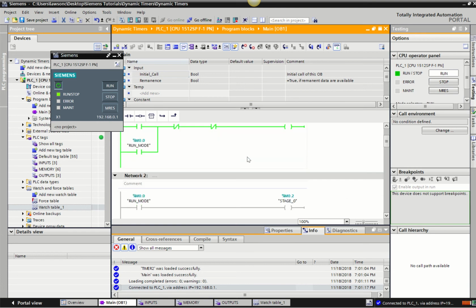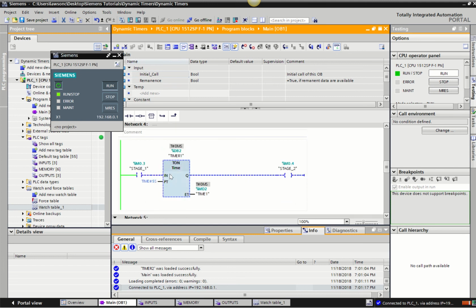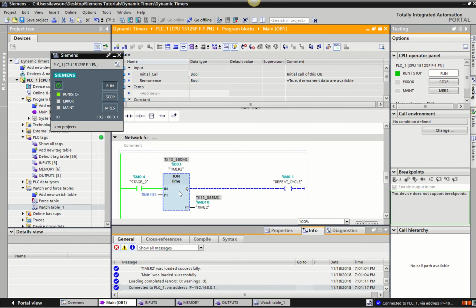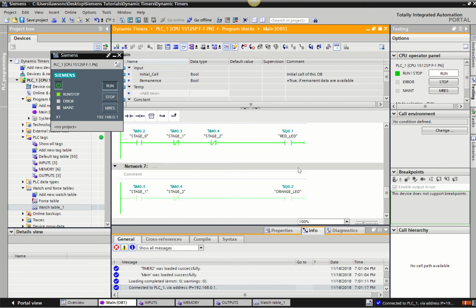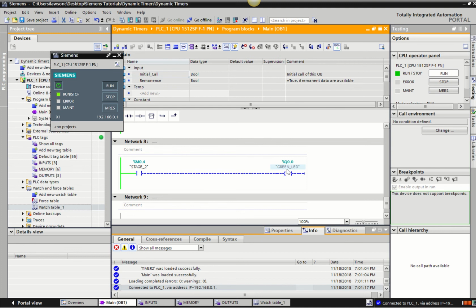We go from the very start, run mode gets turned on, and ultimately we're starting a timer, turning on another stage, and then feeding into another timer. You see that there, feeds into that timer. Then eventually this one will come on and feed into this one, and then that allows us to repeat the cycle. And we're using ultimately those markers to turn on and off. Okay, so that's just our standard setup.